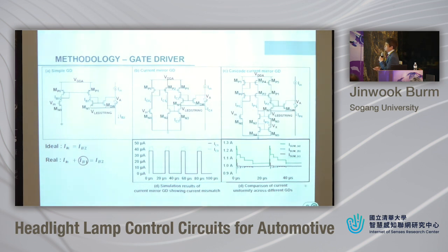This can be shown as a graph over here. For this time-varying case, we change the conditions. For each different part, the PWM signals are all different, from high value to low value. In this curve, the A, B, C cases are plotted in one graph. For the C case, plotted in red, we can guarantee a quite flat current throughout all these LEDs. While in the A case, the currents are high, as high as 25% above the normal current of 1 milliamp. But by using this C configuration, we can maintain the current at about the same level.